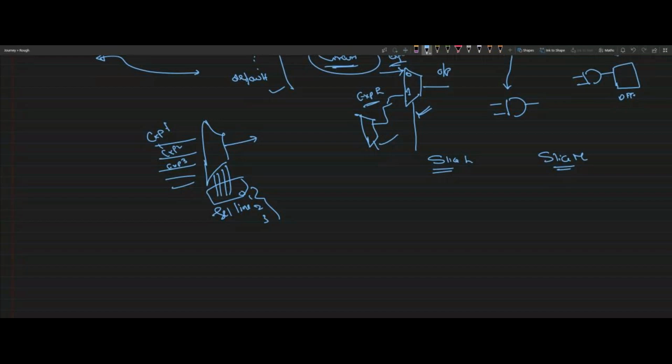Also, in one CLB there are more slice L cells compared to slice M cells. In a CLB we will have 2 slices. CLB is also of 2 types. Whenever I say CLB LL, both the slices are slice L. If I say CLB LM, one slice is L type and one slice is M type. It depends on which series of FPGA you are using, the proportion of CLB LL and CLB LM we might have.